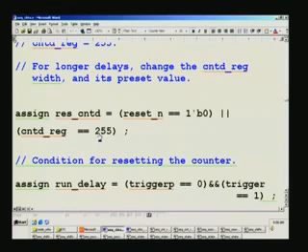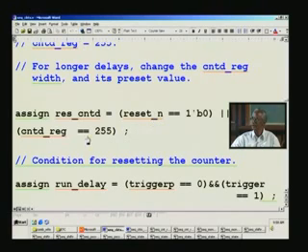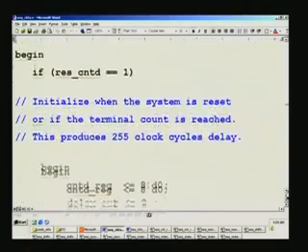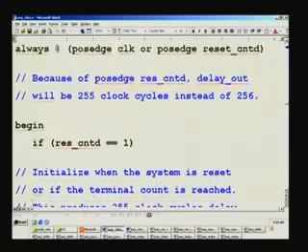And the moment that happens, this goes to 0 because this is a combination circuit. So this is nothing but an OR gate. So the moment counter touches 255, immediately after a delay of this OR gate, right, this will get reflected here. So are you getting it? If this happens, what happens to this statement? That is reset counter D, right? So what has happened here is, follow this carefully. This is the crucial thing.